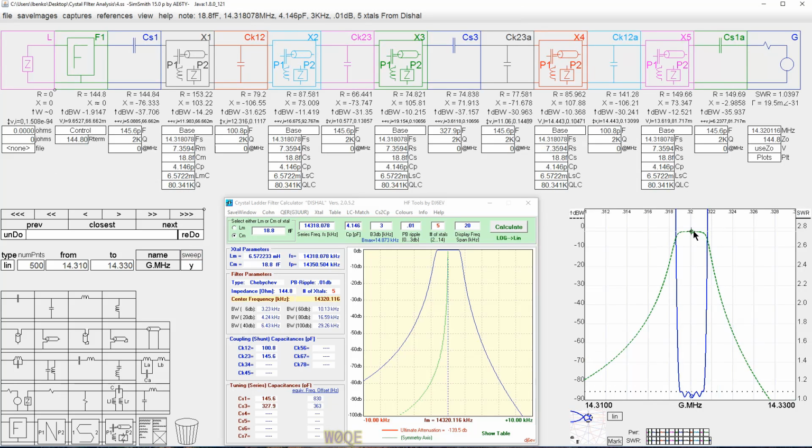And what we're seeing here now is the passband increased, the loss increased in the passband. It was 1.4 dB before, it's 1.9. So asking for the filter to be narrower will always give you more loss in the passband. The impedance it matches changed, and I've matched these again at the same time. I've done a lot of work in here. Each time I change one of these things, I've gone in and filled in all the values.